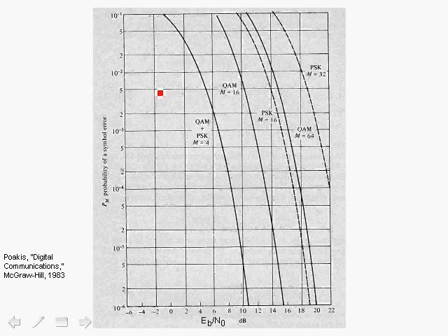This is a very important diagram which plots the probability of error, probability of the symbol error, versus the EB over N0 ratio. So the EB over N0, where EB is the energy per bit and N0 is a one-sided noise spectral density. And recall that we derived this expression, the probability of error versus EB over N0, for the case of binary signaling, which is equivalent to BPSK.